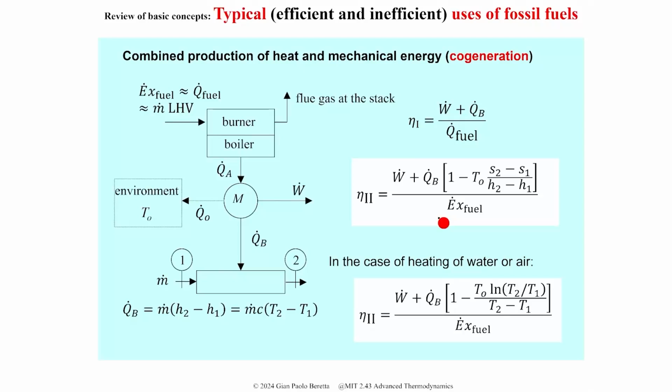And again, this is the same thing where we highlight that if the temperature of what you're heating is changing, you need to put in the logarithmic mean temperature.